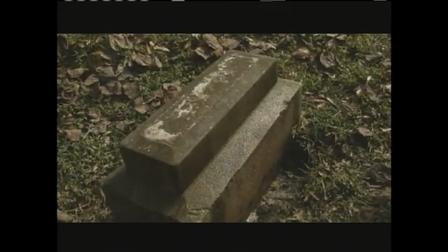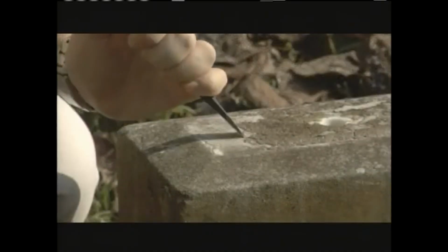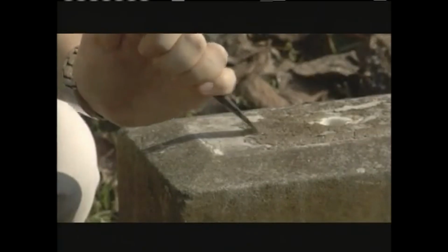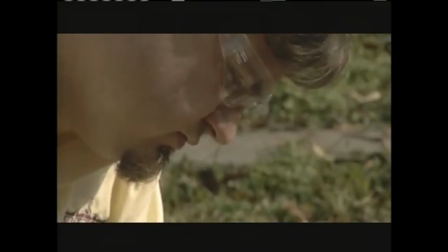The next thing that we notice about our base are the traces of the old failed hard mortar. We must remove any loose mortar to get a good bond when the stone is reset. We are going to carefully remove the old mortar with a hammer and chisel. This procedure will need to be done to both the base and the headstone.